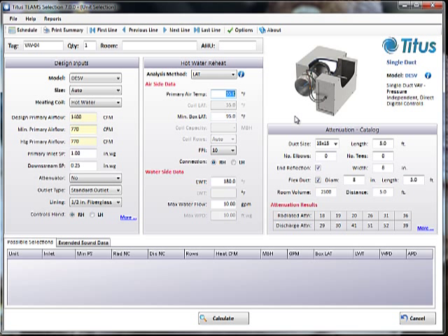So I'm going to leave it at leaving air temperature. We'll say 55 is our supply. We actually want to go about 90-degree leaving air temperature. You can pick between 10 fins per inch or a high capacity 12 fins per inch as well. You can do right hand or left hand. Entering water temperature, max water flow, I'll leave those where they are, and now let's say calculate.